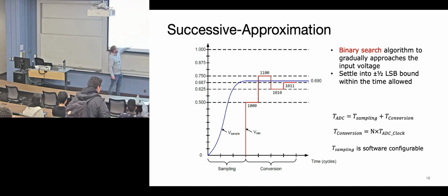Here they're showing a sample, assuming that you start at 0 and ramp up until some threshold value, and let's assume that the drive strength of the analog signal coming in is fast enough so it comes to some steady state before my sample time is up. Some assumptions can be made. You can adjust your sample time in your dev kits if you needed to.